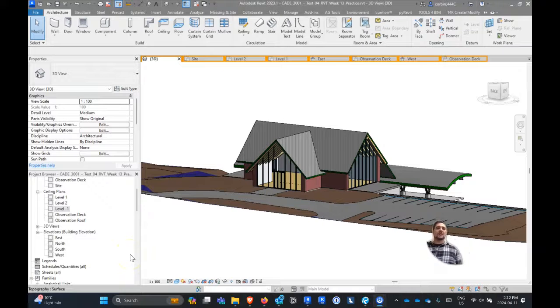All right, so we have our building here, and for quiz 5, as I mentioned, our goal is to convert what we have here into a template. And so the one thing I like about doing this exercise this way is right now we've already built some stuff, right? We've loaded in some columns, we've created some floor types. And so when I was building my templates really early on, I would often take my most recent project, strip it, and build that as a template. So that's kind of what we're going to do today.